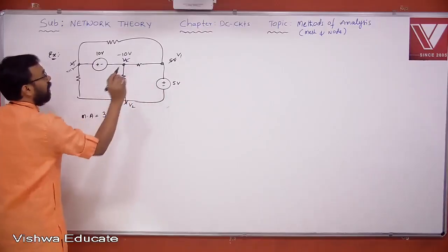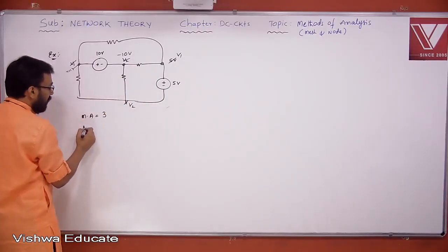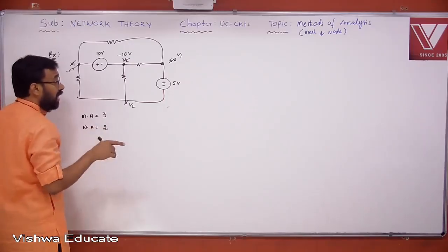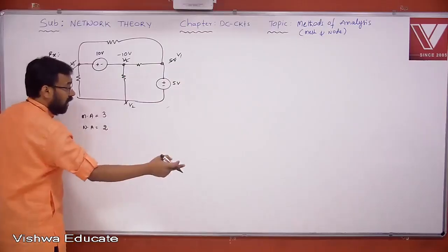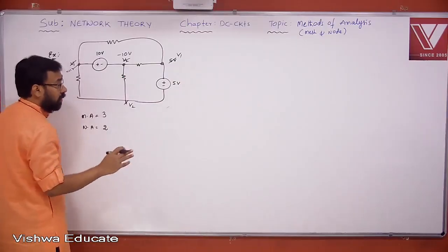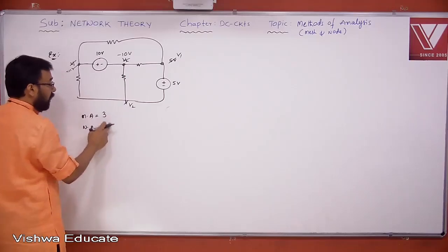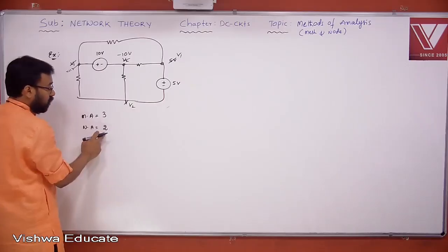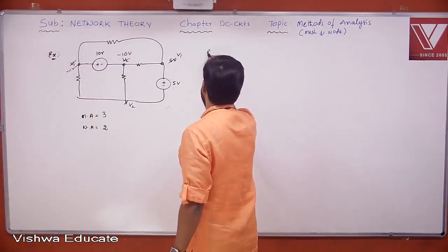So what are the minimum number of equations required? Okay, in this particular problem, using node analysis will give you 2 equations. How many nodes are there? 1, 2, 3, 4. How many equations are required? Not 4 minus 1, because ideal voltage sources without resistors are there. Therefore, that condition fails, n number of nodes, n minus 1 equations, and finally you got, with the proper selection of reference node, 2 equations. Understand? Okay. Now let us look at another example.